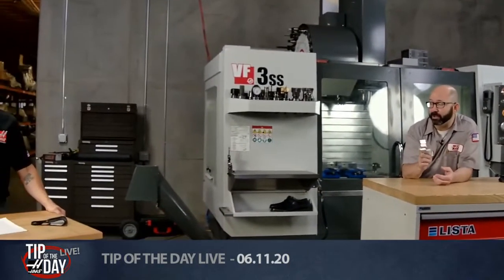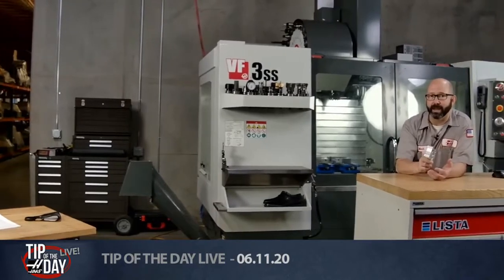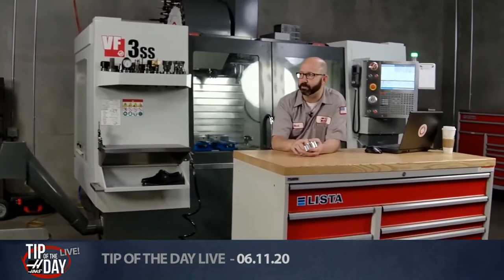So it's all built right into the control. So you don't have to worry about that. Right, the answer is yes. The answer is absolutely yes. But when looking at a machine, be careful, because a lot of manufacturers don't do that. You buy a 5-axis machine, and it's not a 5-axis machine, it's a 3+2. It can't actually run those axes at the same time.